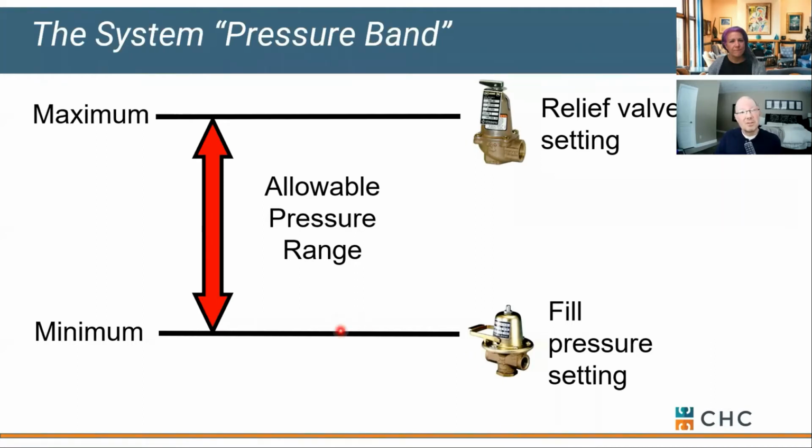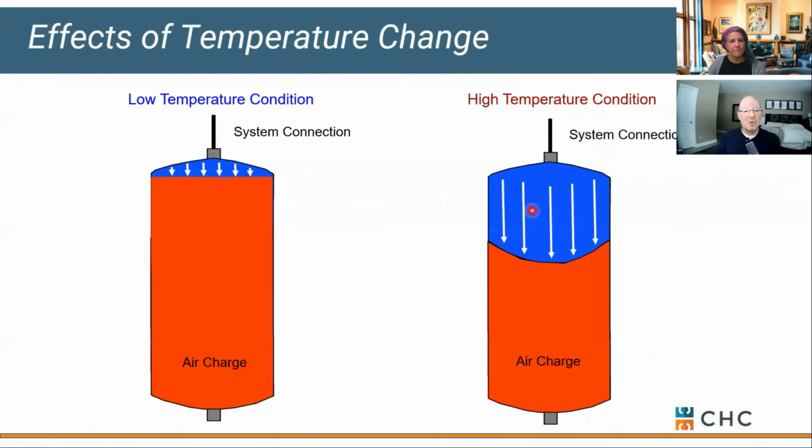We start our boiler again, guess what? Same problem. Relief valve opens, we send more water down the drain. So our chemical balance gets out of whack. Not only that, most boilers are designed to operate in a closed loop system, not an open loop. If we're making up water every time we cycle the boiler and we're dumping it down the drain, is that still a closed loop system? I don't think so. So the reason we use expansion tanks is to keep our closed loop system closed.